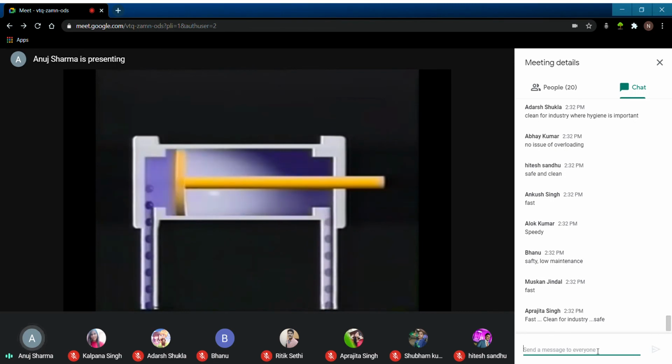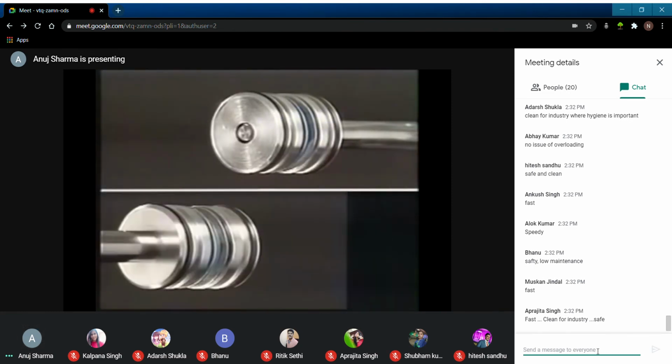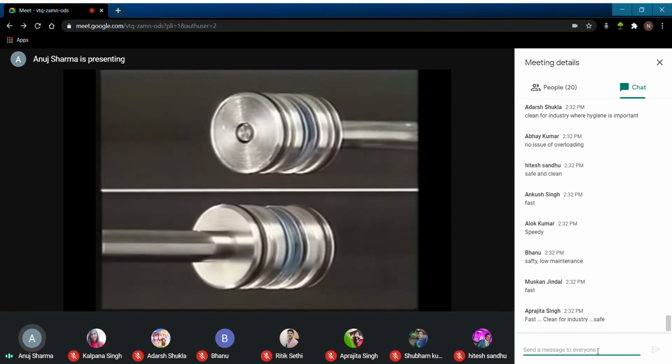In a double-acting cylinder, the force exerted by the compressed air can be directed against either side of the piston. This allows work to be done on both the extend and return strokes. Note that the area occupied by the piston rod also reduces the force generated on the return stroke. Due to the area occupied by the piston rod, less air is needed for the return stroke.